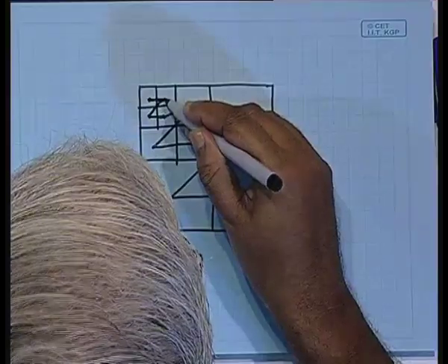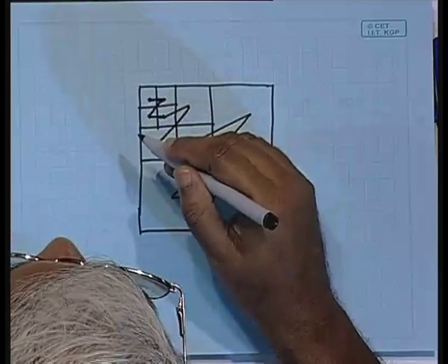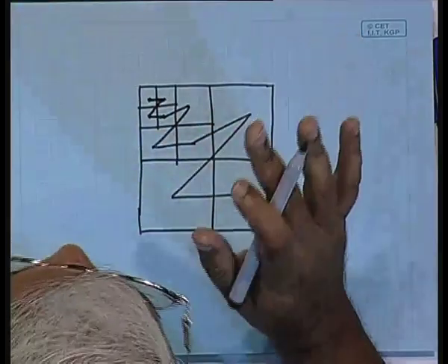Since you are traversing a tree like this, you form a tree first, and then whenever you are traversing the tree in this order, if you find that a particular coefficient at the higher level of subbands is insignificant, let us say 0, and if you find that all its descendants in the tree are also 0, in that case there is no point in encoding each and every 0 coefficient.